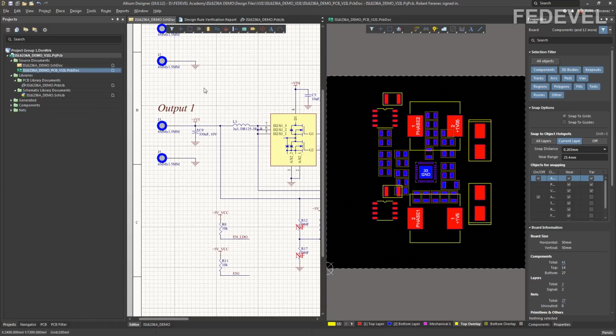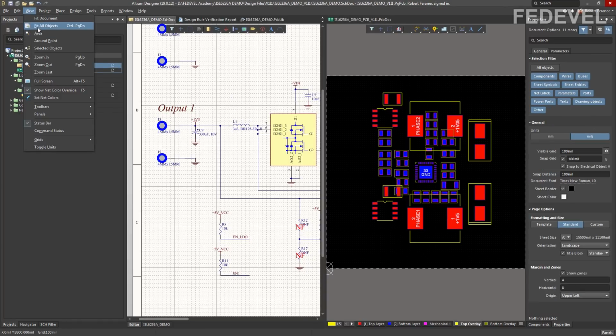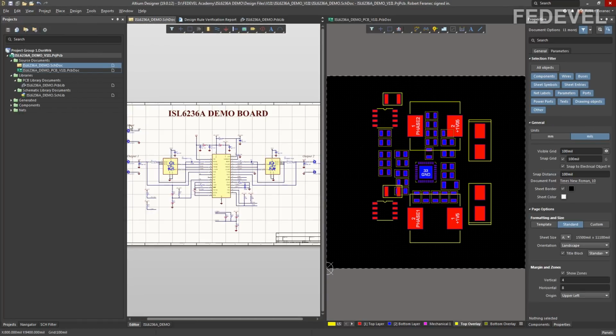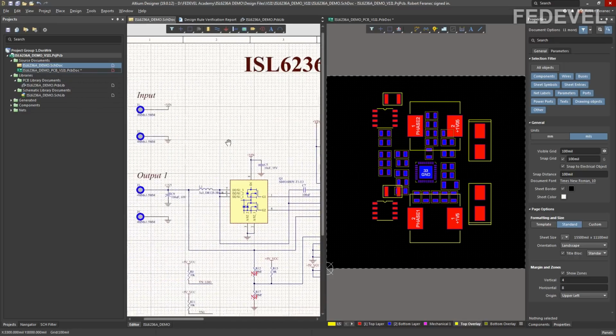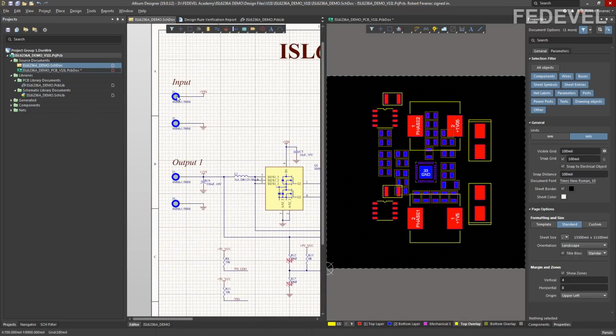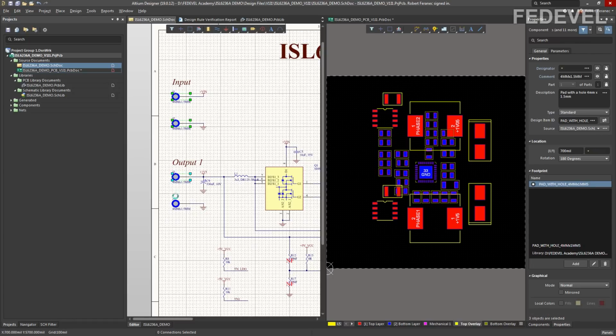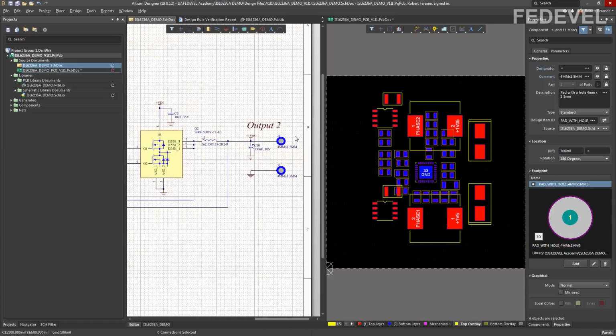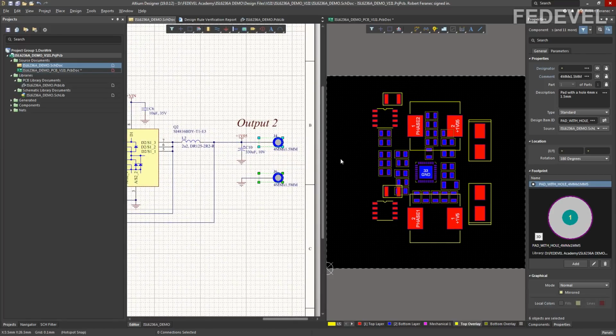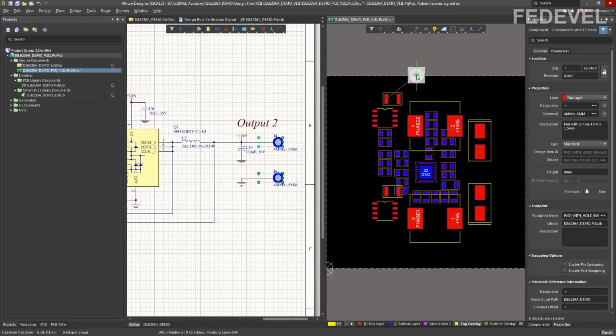Zoom out the schematic, and only what is left are the paths, and we would like to place the paths again on nice locations, so do it this way. Zoom in, select all the paths, left click, press shift, hold it down, left click, left click, left click, left click, left click, reposition selected components.